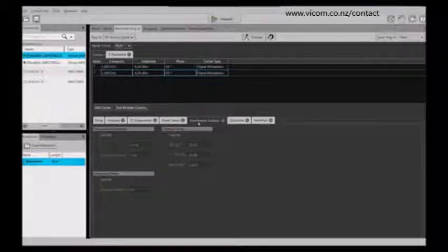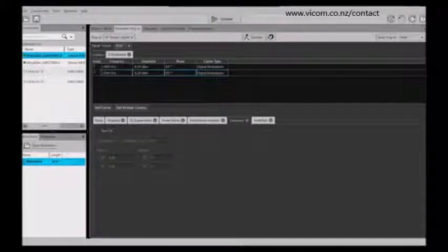We can also do interference addition, so if you want to add noise or sinusoidal interference, you can do that with the tool. So this gives you all the flexibility again for creating those real-world type waveforms. Distortion, another feature that many customers are using for their testing, is to be able to turn on a nonlinear distortion, soft limiting or hard limiting distortion, and you can specify the operating point at which you want this to be enabled. So again, this is a very useful feature for doing specific receiver testing.